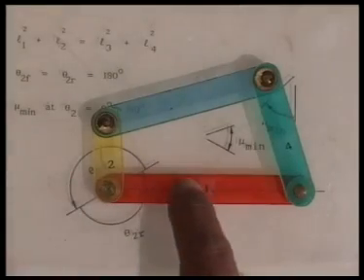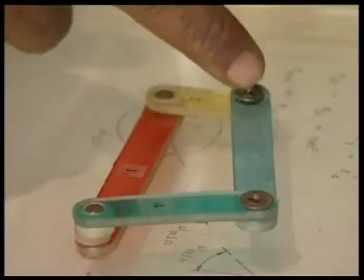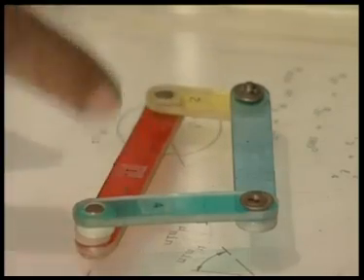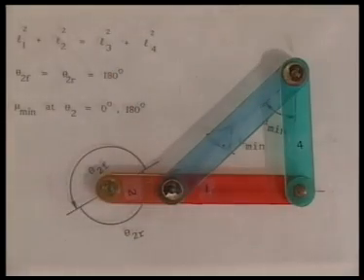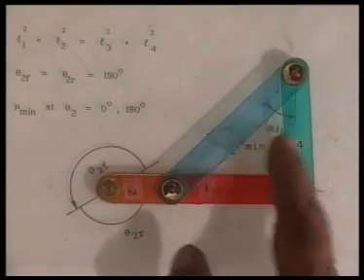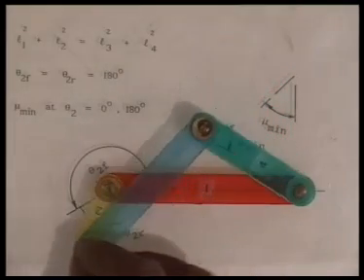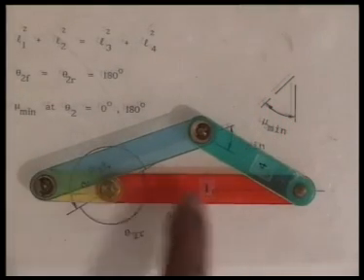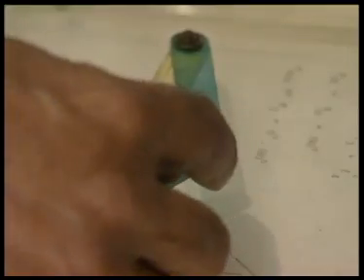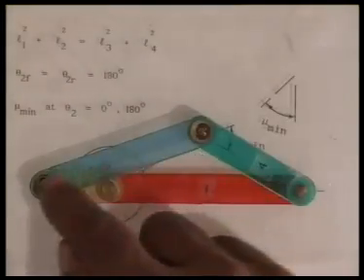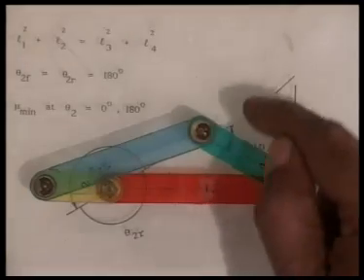We consider this model of a Crankrocker linkage without any quick return effect, that is L1 squared plus L2 squared is L3 squared plus L4 squared. For such a linkage, as I told you, the minimum transmission angle occurs when the crank is along the line of frame. This angle between the coupler and the follower reaches its minimum value. However, again when the crank falls along the line of frame, this angle is maximized, that is the transmission angle, which is defined as the acute angle between the coupler and the follower, that I can see by extension of the coupler and the follower, that angle is minimized.